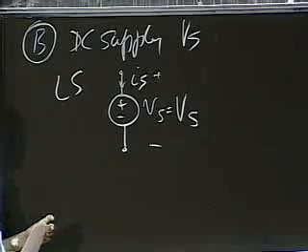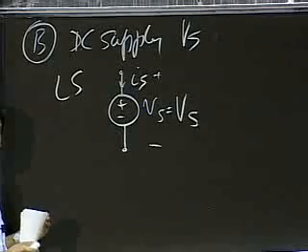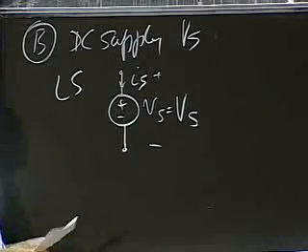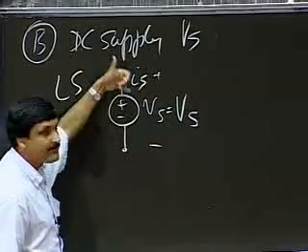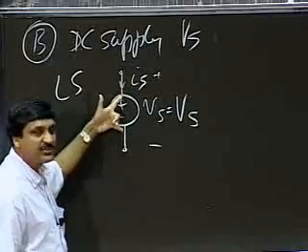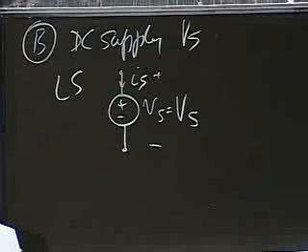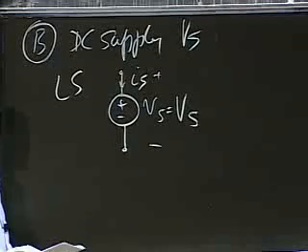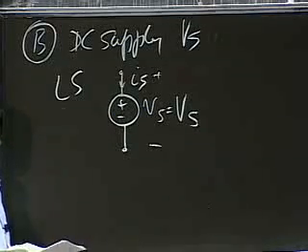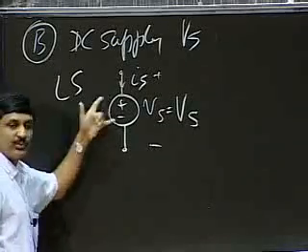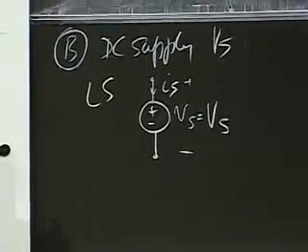So what do you expect to be the small signal model for a voltage source? In other words, suppose I have a small change in the current. By how much should the output Vs change? It shouldn't change. It's a voltage source. So what does the intuition tell you is a small signal model for a voltage source? A short. So the key here is that a voltage source behaves like a short circuit for small perturbations.